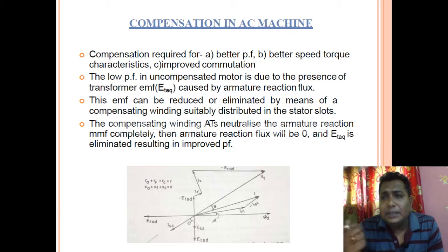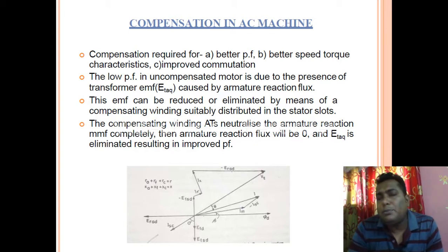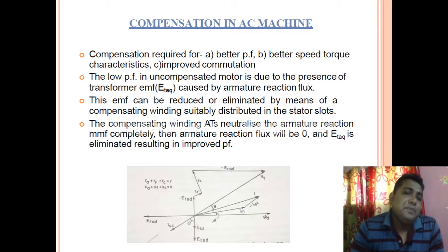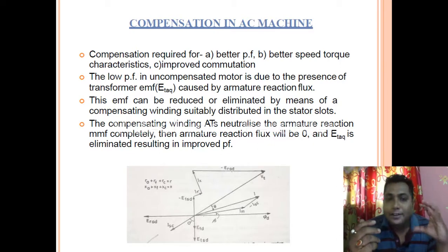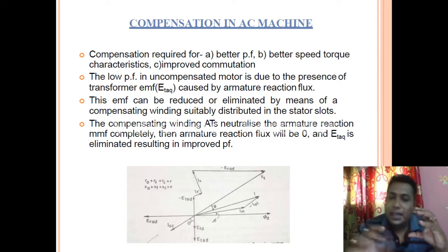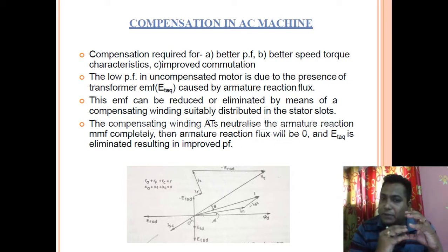And when this rotor winding is connected to some sort of load, here also some current flows, and due to that current flow it is itself generating some flux. So that means we can think of it that way: in the stator we have a flux, in the rotor we have a flux. Okay, so this generated rotor flux will try to destroy the main field flux.